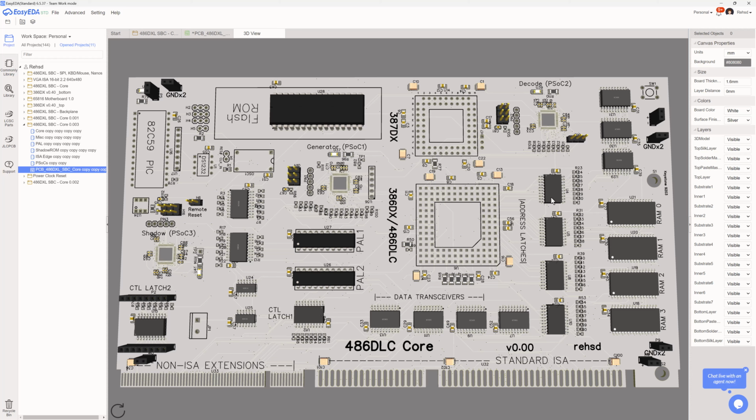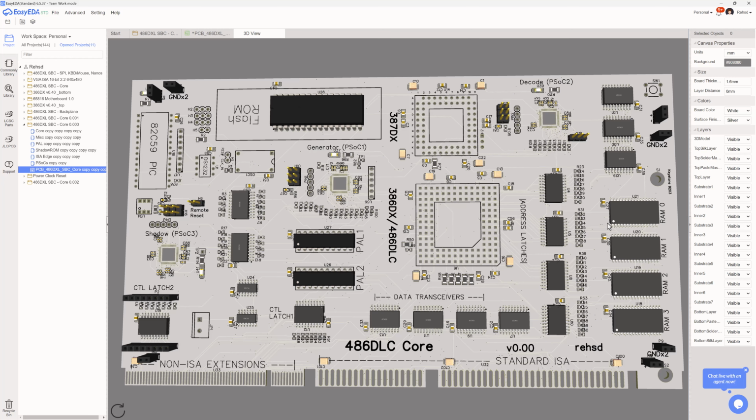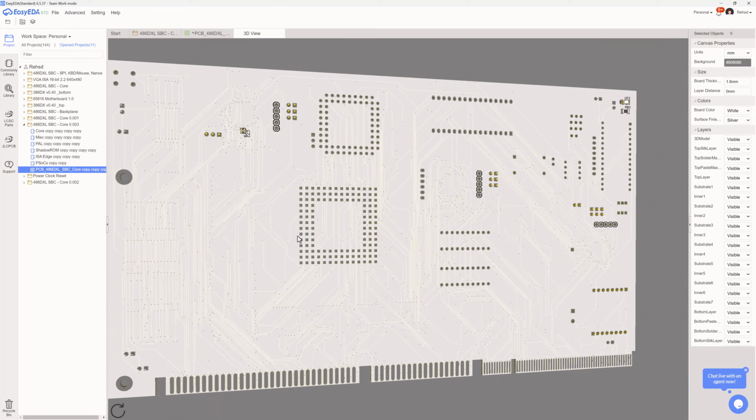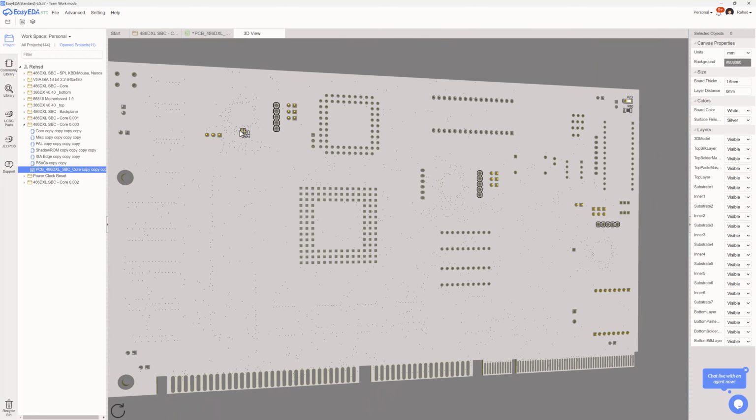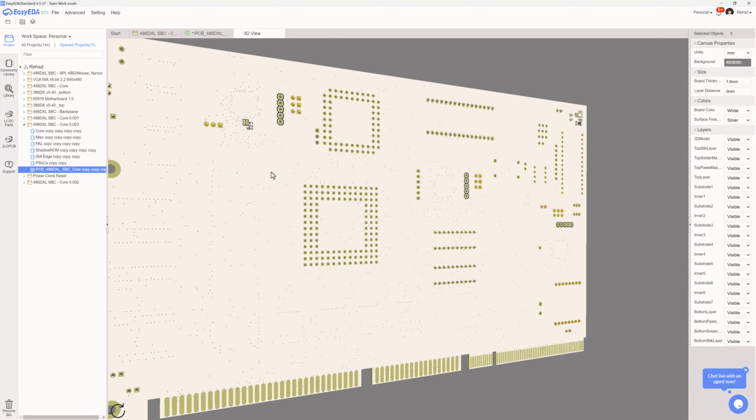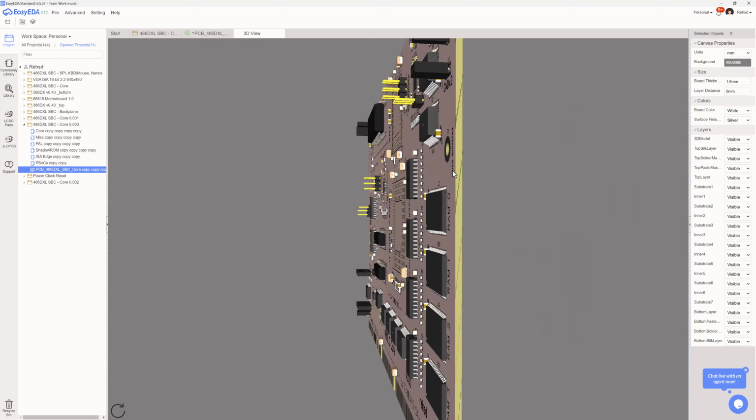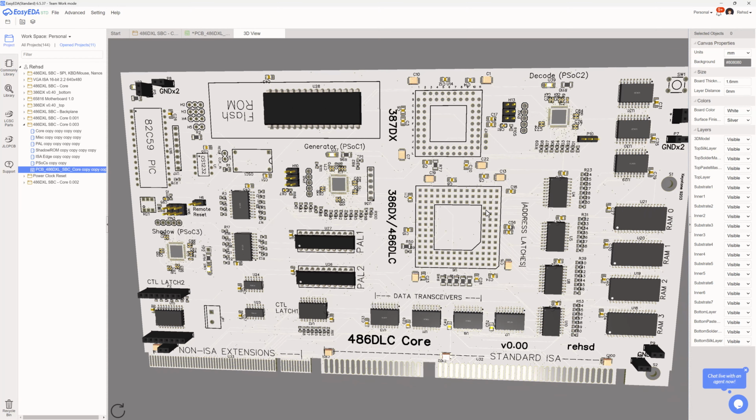So if any of you are experienced on placing components front side and back side on a 4 or 6 or worst case 8 layer PCB and have suggestions of what type of components here might make sense to throw on the back, let me know your thoughts. But right now I've got this all on top, other than some that it looks like I missed when I wanted to pull it back. So that would be a couple of these on this upper P-sock, and that looks like P-sock number 2. So I'm going to jump over here to P-sock number 2 and correct that real quick.